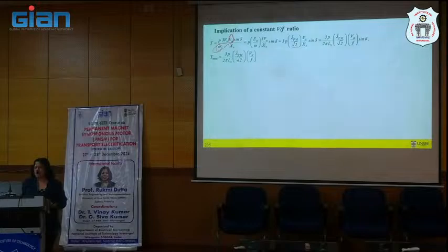So EA over omega is a constant. Even if we change omega, that means EA is going to change proportionally, so it's kind of constant. But if we change omega, we still have a problem with the synchronous reactance part, right?